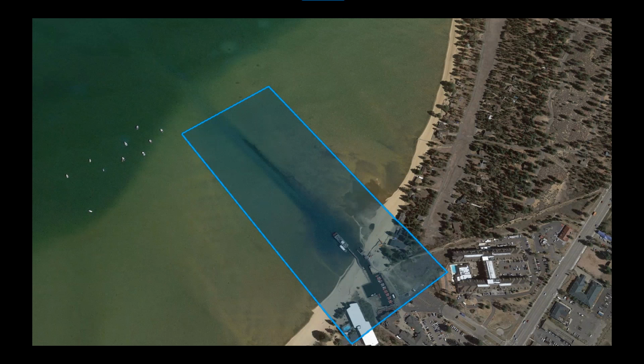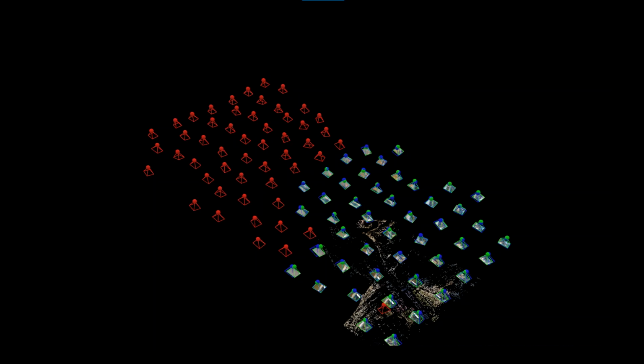And the next slide here, we're looking inside our photogrammetric software and looking at where the photos failed to match to one another. Okay, so all those red ones that you see there, those are images that could not be ortho-rectified. So we've got data loss. The reason why there's data loss out there is because we're over water, there was a little bit of wind, it cannot find matching points between those photos. So as a result, we're only getting imagery closer to shore. So your choices there are really to try to fly at a higher altitude, keeping in mind the FAA limits, and getting as much of the shoreline as possible to ensure that you have tie point matching.